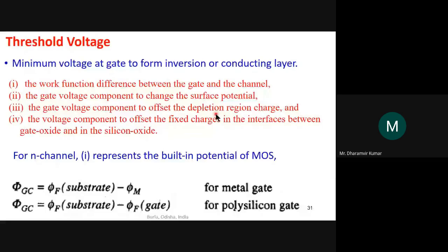Although the depletion region does not contain any moving charge, we know that it consists of impurity ions, and impurity ions have some charge, either positive or negative. Although they cannot move and will not contribute to the formation of current, since they have some charge, they will generate their own electric field.